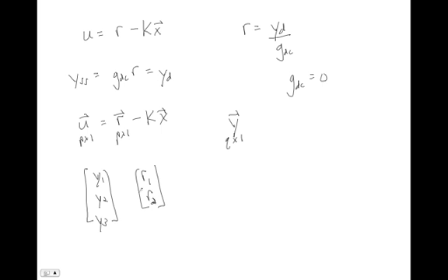I think it's reasonable to ask yourself, is it possible to set all 3 outputs to values we want using only 2 inputs? If we have fewer inputs than outputs, is it possible to establish all of those the way we want? It may be reasonable to think that isn't really possible. It also may be, what if instead we have 2 inputs but only 1 output? We have 2 different inputs and 1 output. Which of these inputs should we be setting to y desired over DC gain? Is that really a well-defined problem?